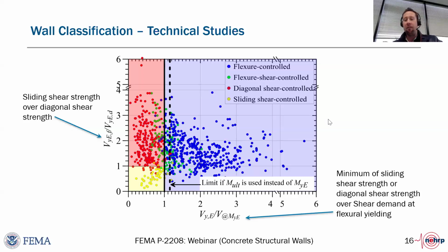We're going to use that value as your ultimate moment capacity. And if you look at the shear associated with that flexure capacity, are you expecting that your shear flexure controlled? That helps us, with more confidence, to be sure we have all the shear controlled walls covered. And in general, you're going to capture more of those diagonal flexure shear controlled interactions.